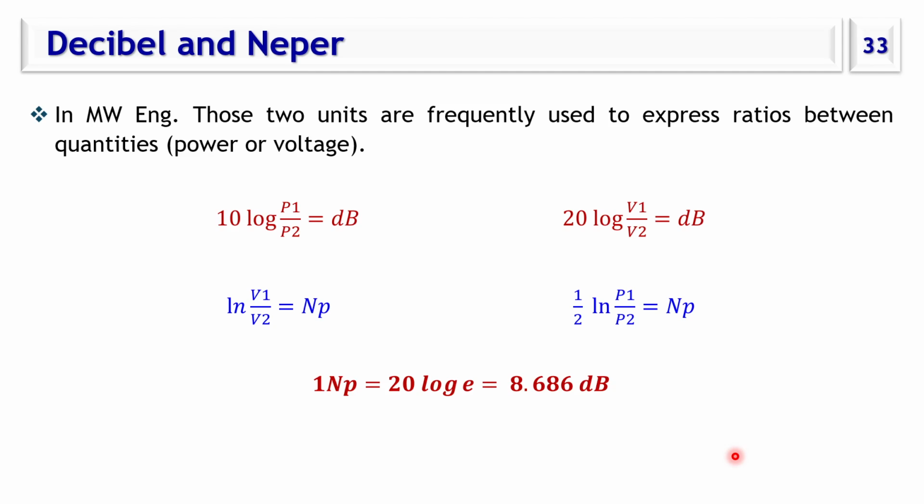So we're dealing with dB, and in engineering we frequently deal with this dB quantity, just to have more sensitivity to a wider variation range. If we are talking about the ratio of power, it will be 10 multiplied by log. If it's a ratio of voltage, it will be 20 multiplied by the log. There is another quantity, the neper. It's the natural logarithm: half ln for power, and for voltage it is the ln, and you can say that 1 neper equals 8.68 dB.